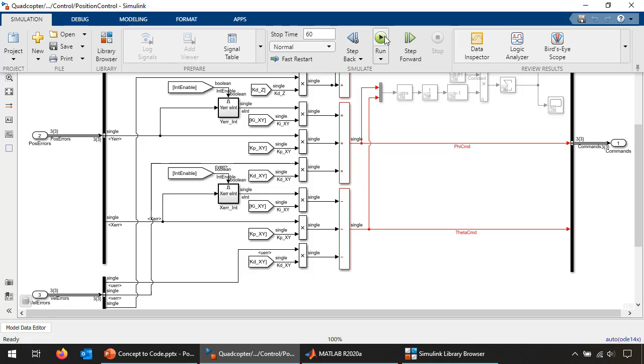If you need to, you can make this process more formal than pushing the play button by hand. It is possible to invoke a Simulink model from the MATLAB command prompt with the sim command. There is also a command called parsim that is going to enable you to create a whole batch of simulations that you want to run.